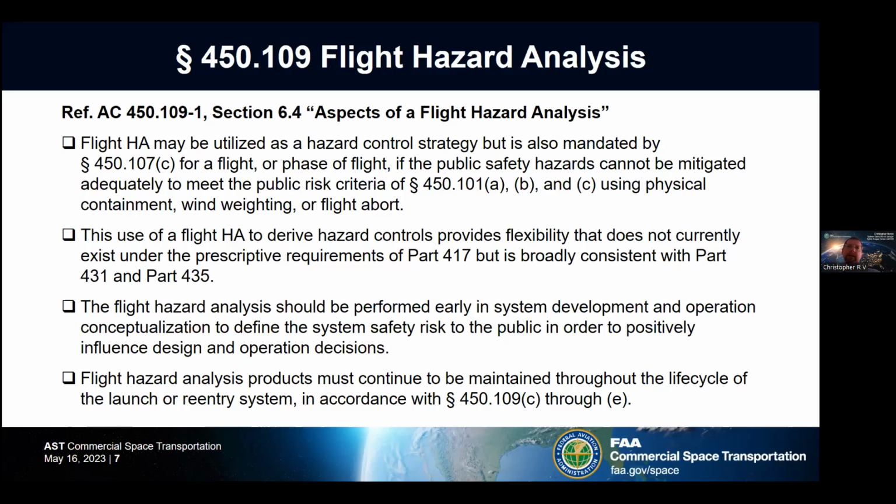Flight hazard analysis should be performed early in system development along with the rest of the system safety, including the functional hazard analysis, during system development operational conceptualization to define the system safety risk to the public in order to positively influence design and operations decisions. And the flight hazard analysis products must continue to be maintained through the life cycle in accordance with 109C and E. Next slide.